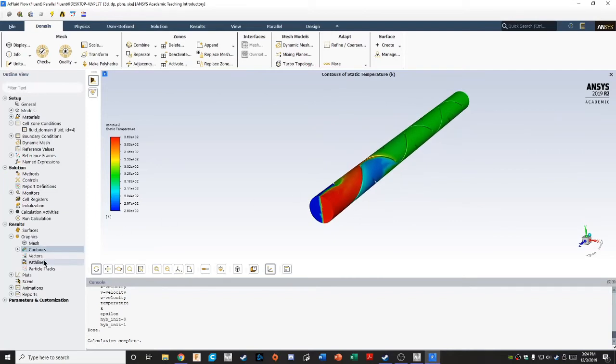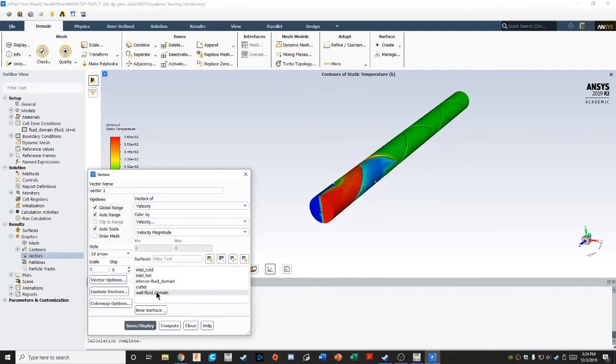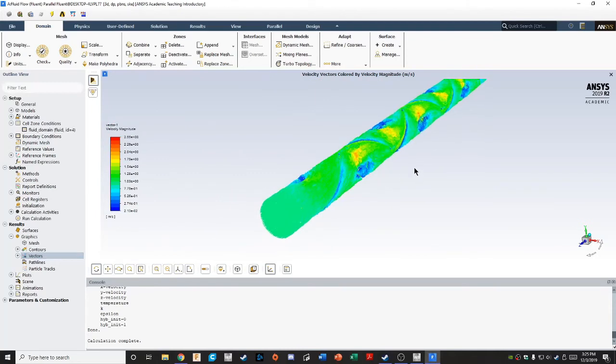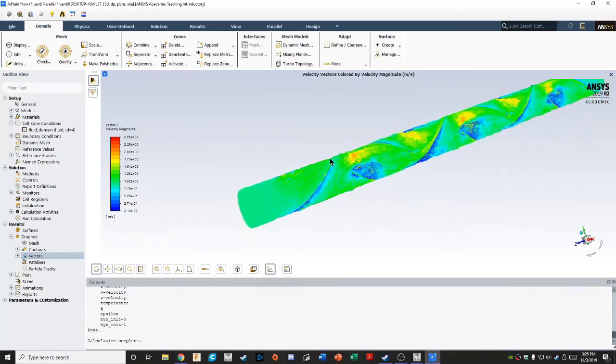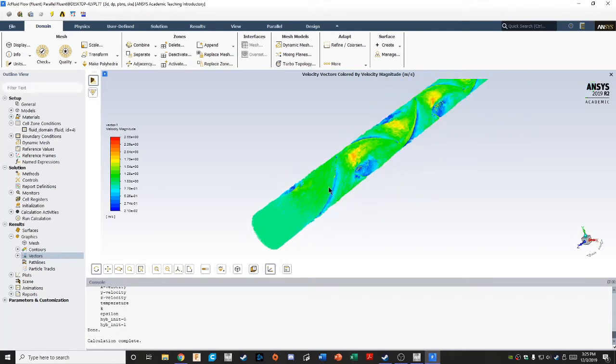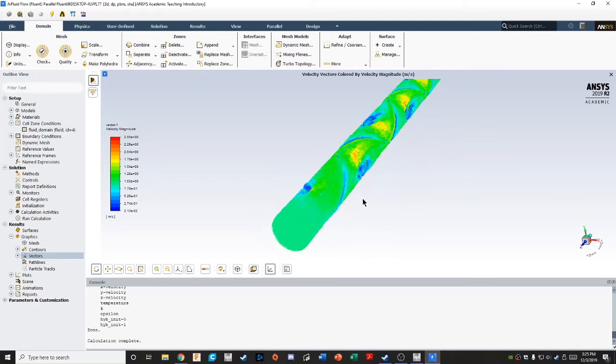And then finally, we're gonna add our velocity vectors and just see how they end up looking. So you can see it's pretty dense, but you can see at the edges of each of those baffle cuts, the velocity is very slow. It's building up pressure around there. And then at the interchanges, you get a significant boost.